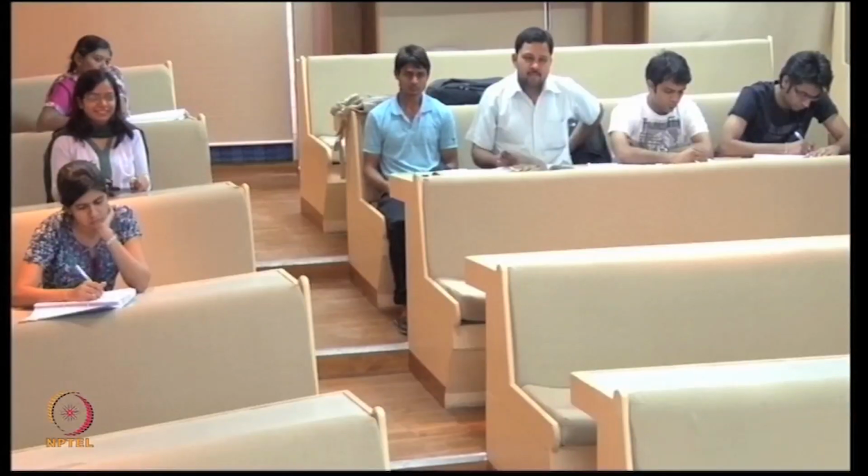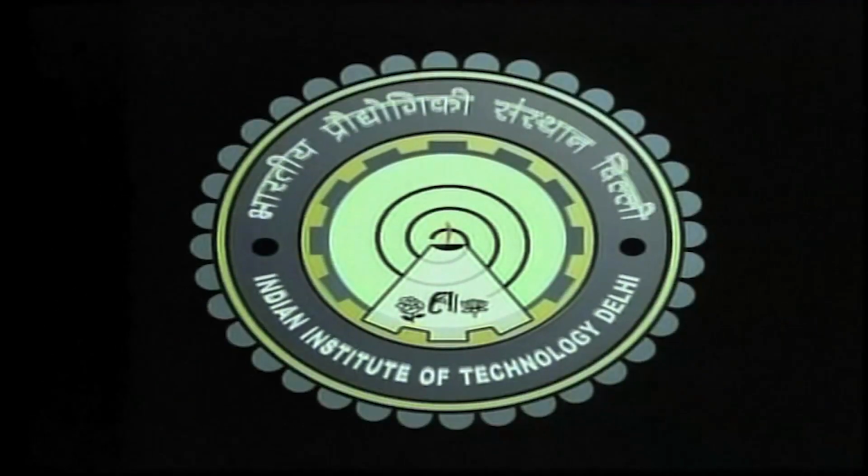I will just answer that question and we will stop here. It will be of the order of 10 picoseconds, 10 raised to minus 11 seconds. That means it is such a short time that only for that brief moment the gas phase resistance is controlling. Beyond that time, it is liquid phase resistance all over. So, we will stop here for now.